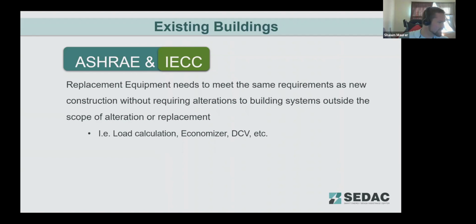I did have a question about the chilled water leaving temperature of at least 57 degrees. Isn't that going to cause dehumidification issues, because chilled water below 50 Fahrenheit is usually what's used for that dehumidification?